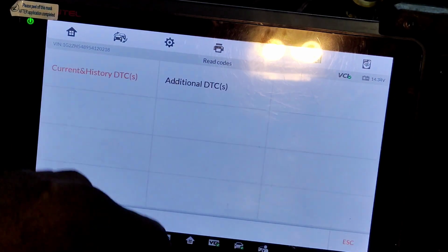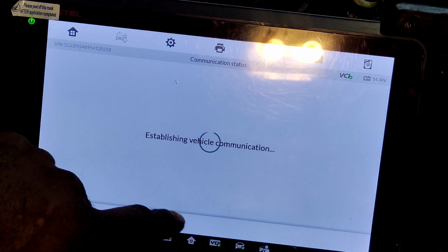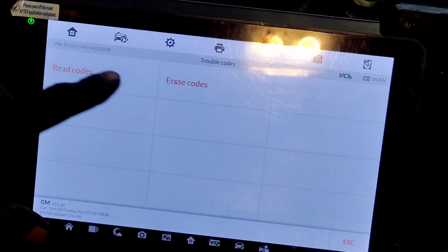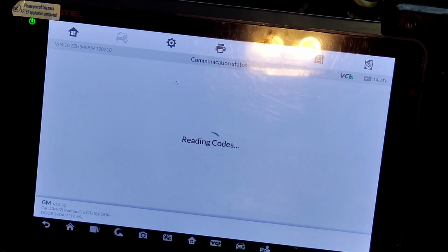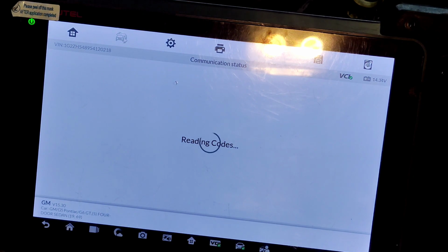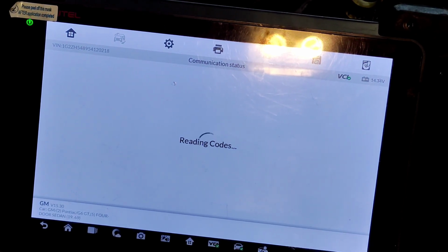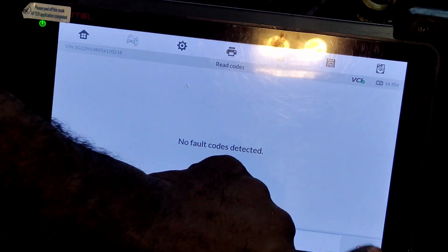That's probably because I had started the vehicle up and they had the EGR valve disconnected. All right, so I'm going to see if there's any immediate comebacks because I plugged the sensor in upside down. So we should have voltage high, so no fault codes. Cool.